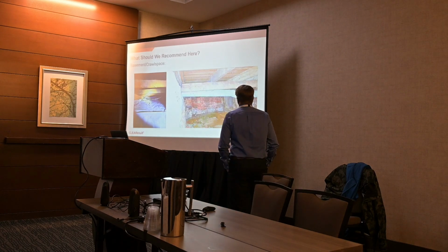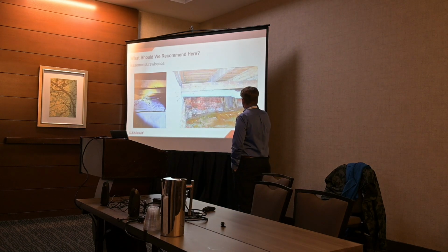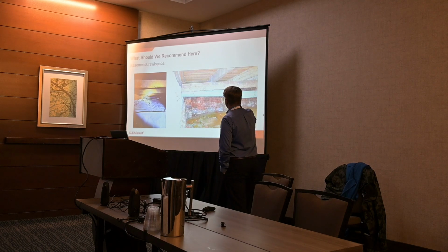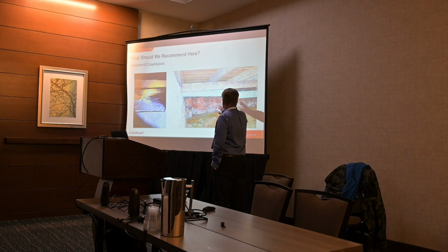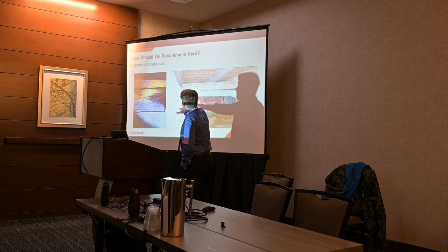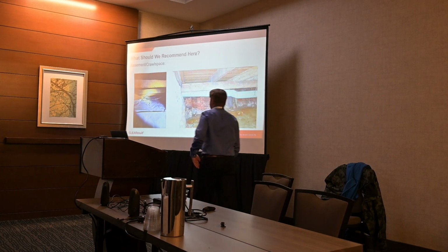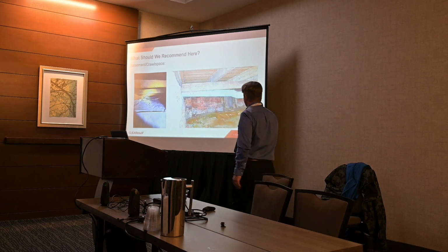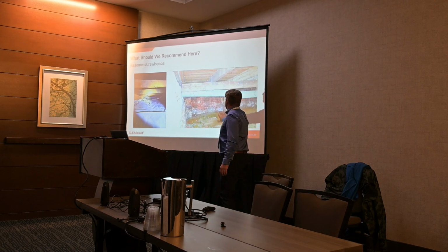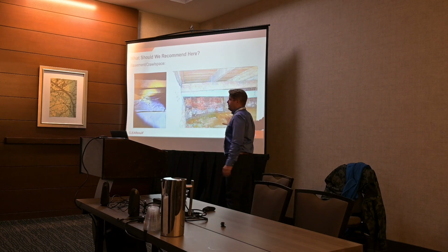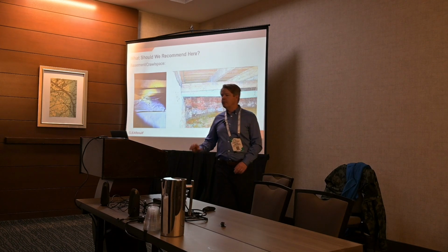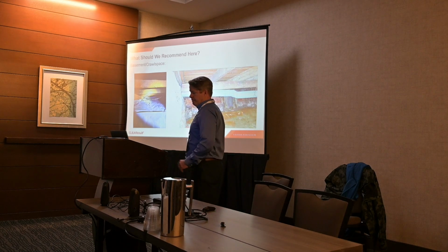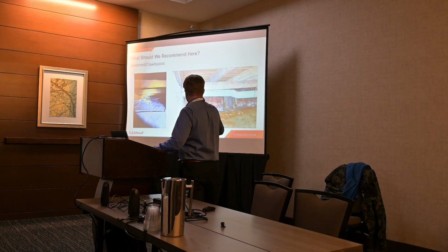Okay, older homes and newer homes on crawl spaces oftentimes can have dirt floors. This is the sort of thing where we want to go from the dirt floor to the class 1 vapor diffusion retarder, 6 mil poly, right? We'd like to pull it up the walls and attach it with either one-part foam or duct mastic, and then seal all the seams nice and tight. Make sure all that water vapor stays down in the basement like it's supposed to, or underneath the tarp.